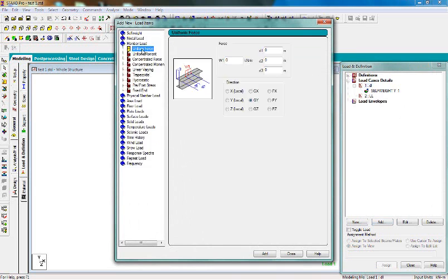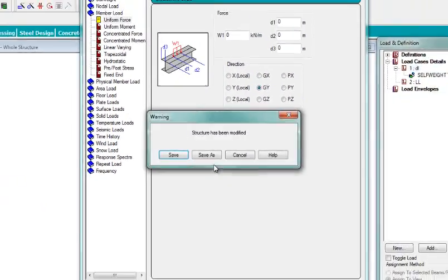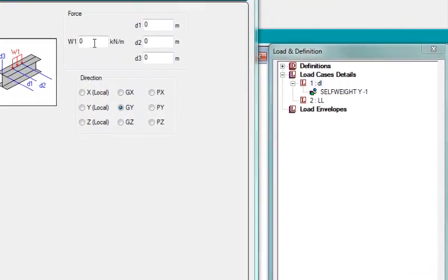here you see there are various conditions like the self weight, the nodal load, the member load, everything. So always go for this and save. For that, you need to go for the member load, and there will be uniform force. We are actually designing it for the uniform force. So uniform force, how much kilonewton per meter?